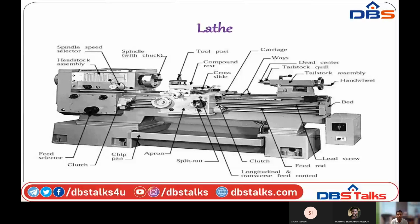Next, I am talking about the headstock and tailstock. Here I am showing the headstock. On the left side, the revolving part is the headstock. It consists of jaws. Jaws are inside the chuck. Chuck is a device used to hold the workpiece. Chucks are of two types: 3-jaw chuck and 4-jaw chuck. The 4-jaw chuck is an independent chuck. The 3-jaw chuck is a dependent chuck. When we rotate one jaw, automatically the remaining jaws move along with that one jaw. In the 4-jaw chuck, we rotate one jaw and the remaining are stationary. This is the difference between 3-jaw and 4-jaw chuck.